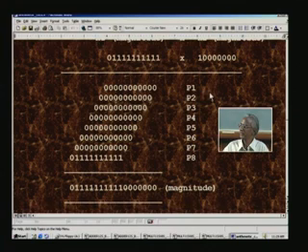Likewise, those 2 when added in the second stage will produce one more output, and similarly from this you will get one more output here. So notice that in the last stage there will be 2 inputs, and those 2 inputs are staggered by 4 bits, because it is the result of these 4 first here and these 4 here. So when compared to the first one and this second group, you have 4 bits: 1, 2, 3, then 4. So the third stage will be 4 bit shifted, and that is how it is.